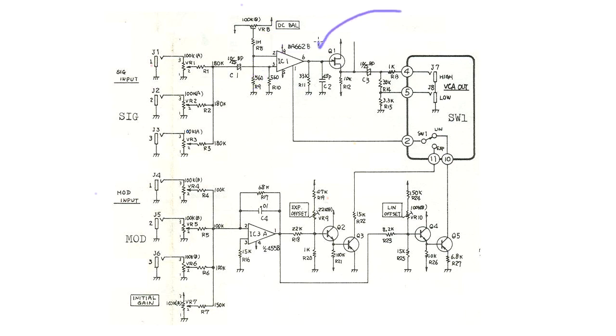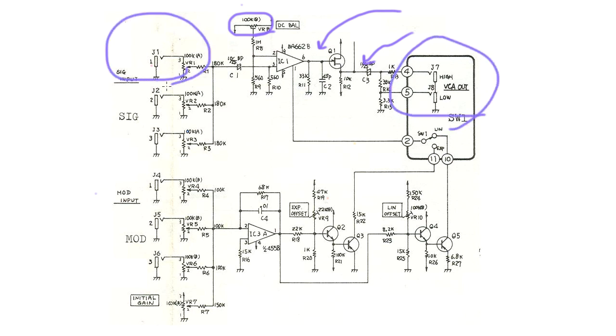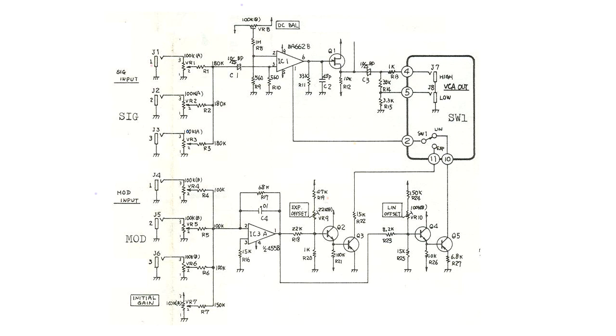Probably somebody at the factory has voltmeters attached to various points, and then they adjust this to try to make sure that the output here is 0 when the input is 0. As usual for my analysis here, I'm going to assume our OTA is ideal, so I'm just going to pretend that this sort of stuff isn't here and treat this input as if it's grounded.